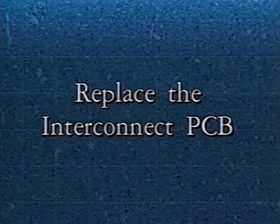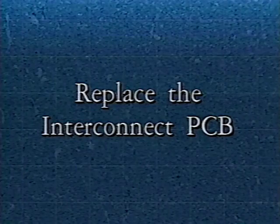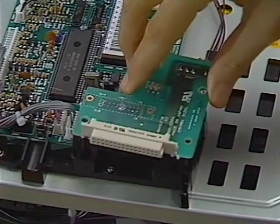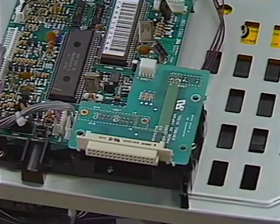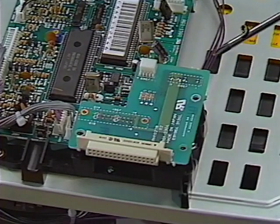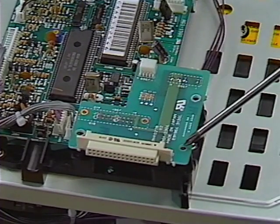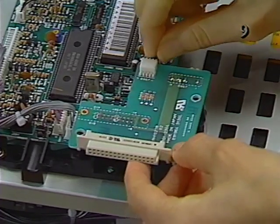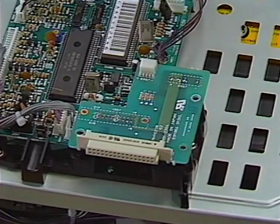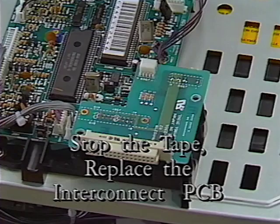Replace the interconnect PCB. First, place the interconnect PCB into position on the DC controller interconnect mount. Replace the three black interconnect PCB screws. Then reconnect connector J303 to the interconnect PCB. Stop the tape and replace the interconnect PCB.